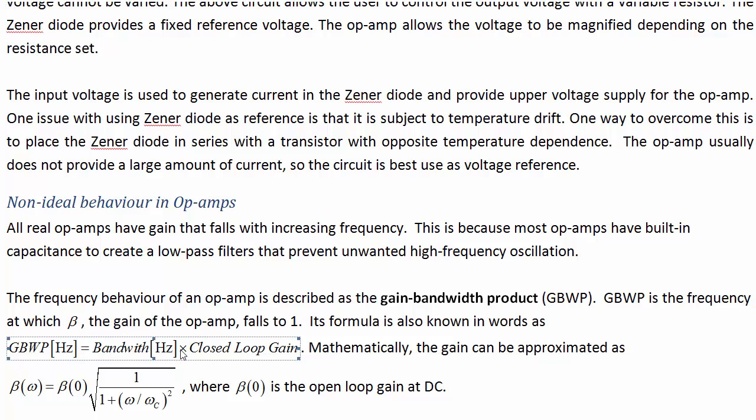If you go above a megahertz, though, then the closed loop gain you were trying to get of 1 is suddenly larger than the gain at that point. So the op-amp is going to behave like a flat frequency response up to 1 megahertz and then start dropping off. In reality, the gain has a frequency dependence that goes like this. So the intrinsic gain of the op-amp depends on the DC gain, its gain at very low frequencies, the current operating frequency, and the cutoff frequency, omega c.